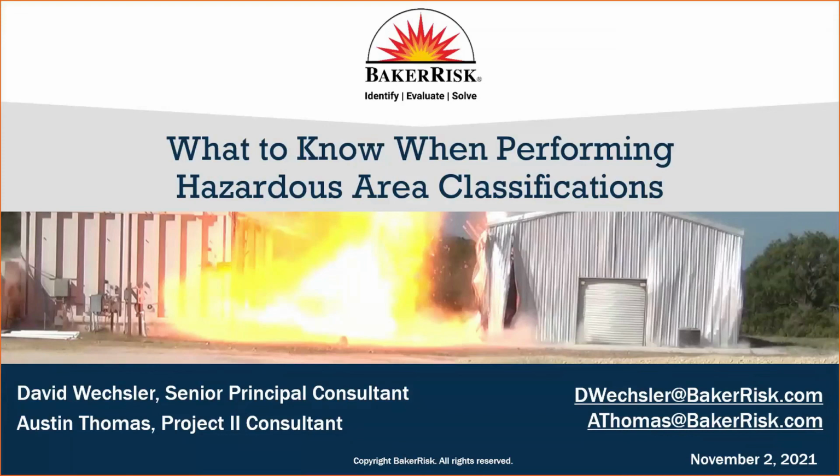Clearly, the hazardous area can control the ignition sources, but again, if you have a highway near your plant and it's 1,000 feet away, the hazardous area classification will not likely address that truck or that vehicle on that highway, but the site scenarios would do that. So it's a question of evaluating your overall risk, and this comes down to the overall evaluation of a site facility risk for your plant and operation.